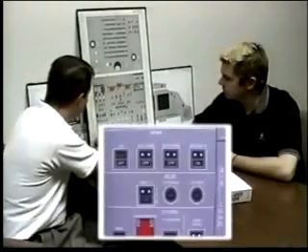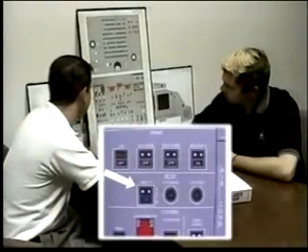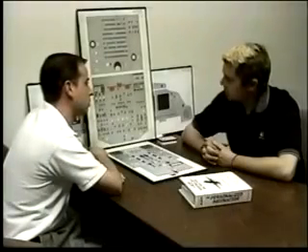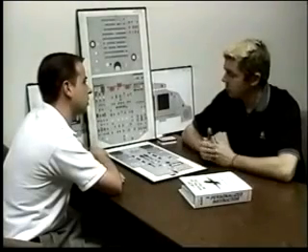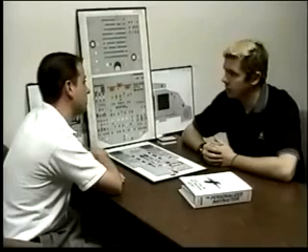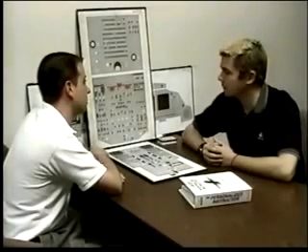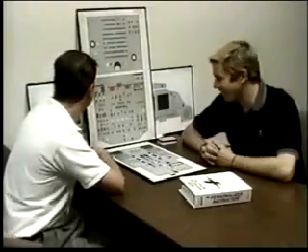Recorder panel. Ground control switch in auto. With it in auto, when does the CVR begin to work? It begins to work for the first 5 minutes after initial power on. It'll also work anytime in flight. It'll also work anytime after the first engine start, which is a good little technique. If you forget anything, think first engine start or green dot. It's going to be one of those two.